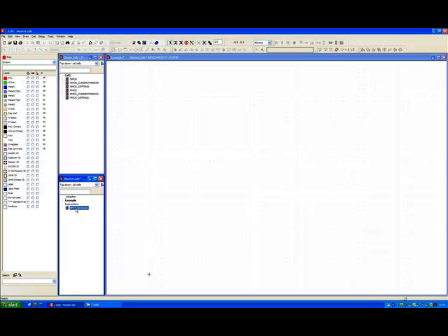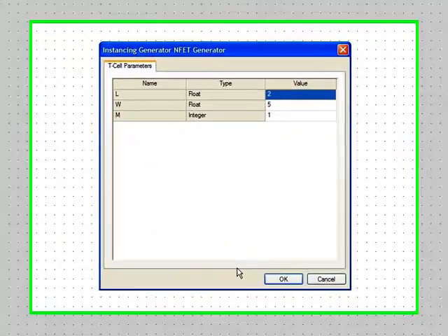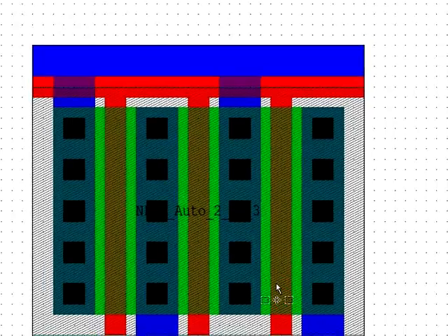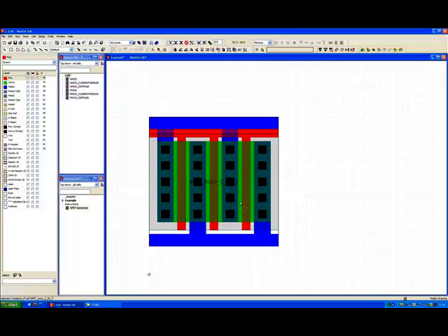As an example here, this MOSFET, if I bring it into our drawing canvas over here and create a MOSFET of, let's say, 20 microns with 3 fingers, and I click OK, what we end up with is a DRC and LVS clean MOSFET device, which can be used from there on in to create the rest of the structure. So we certainly get a significant acceleration that we wouldn't have if we had to lay out this device by hand. And this acceleration is fine, but it is tied to that once-off investment in developing these P-cells.